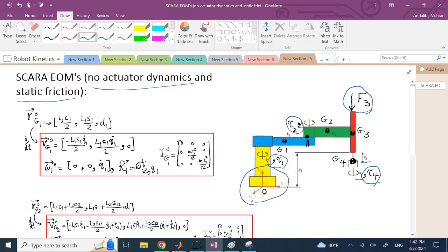So now I'm going to show you the overall derivation of the equations of motion here in one note, but then to get the final equations, we go to MATLAB and use MATLAB symbolic to do all the differentiations for us. So each member here, you can say that it has a translational kinetic energy and a potential kinetic energy. Although for the first member, this blue one, you can say it only has a rotational kinetic energy about this axis, not about its centroid. But if you want, you can just add the two terms for each and every one of them.